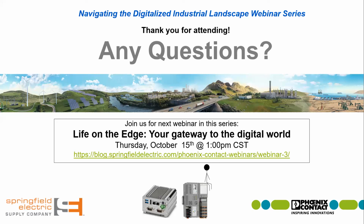So our device is an LTE category 4, which we find is optimized for the industrial space. It's low on power, but it also gives you up to 150 megabits per second for download speeds for sending PLC data, some of that remote communication. And you have to make sure that you get a Cat 1 or above SIM card for our device.